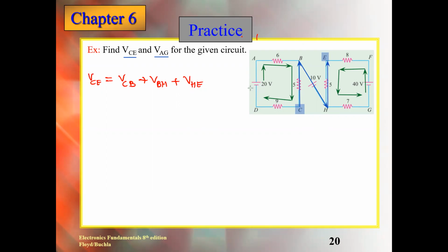So you know that this is a negative sign here, battery terminal. This one is negative. This is positive. You know that. And what will be the sign of the resistance when the current enters from the left side? What will be the sign of this terminal? Positive. Yes, it will be positive and this will be negative. And here the same, positive, negative. Entering point positive, leaving point negative.